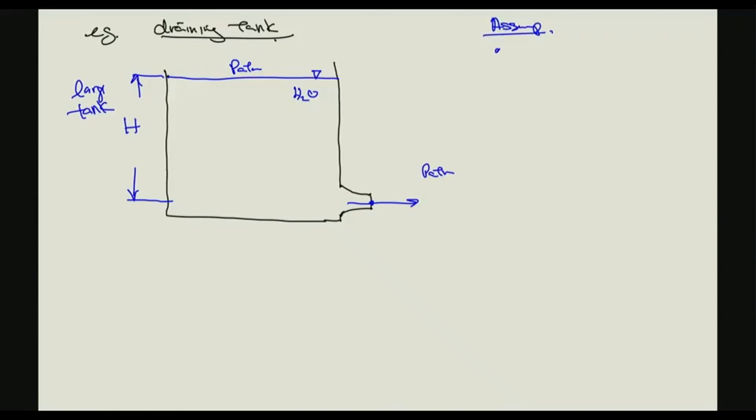In order to apply the Bernoulli equation, we have to have a steady flow. But if we have a tank draining, well, this is one of those problems where the mass is going to decrease here, right? And so in principle, it is an unsteady flow. There's going to be a dm dt in the tank.